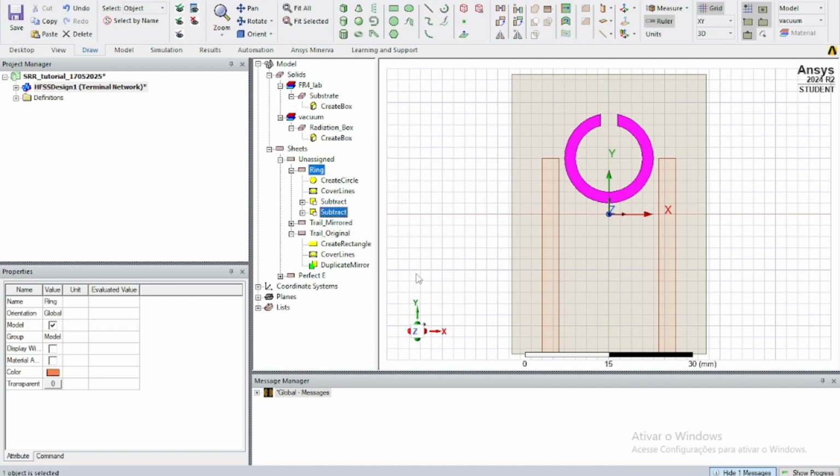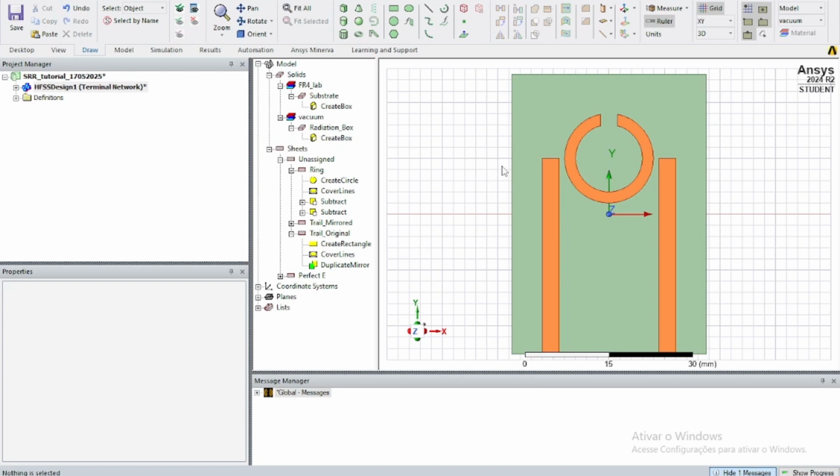Okay, perfect. And now we're going to create the arc that connects these two. So the idea for this is that we're going to create a line here and then an arc in a 180 degree arc, and then we're going to basically integrate this line along the path that the arc forms.